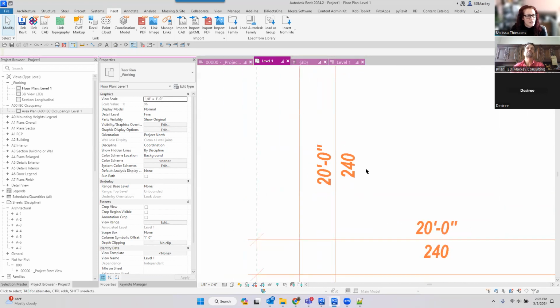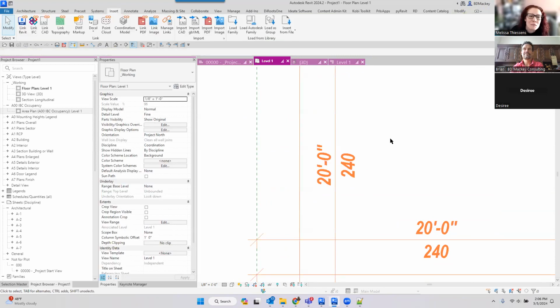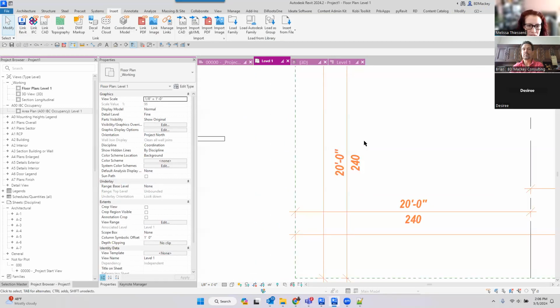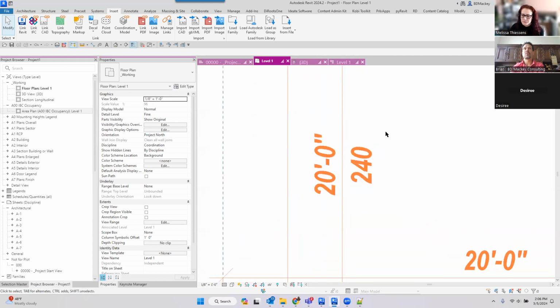I've been doing this for years. So I don't know if it's different if it's metric versus imperial, but I don't get this at all. Is it maybe a very small dimension or something? Yeah, because we have our check one where the bottom dimension is a foot long, but I have it suppressing those numbers if it's not there. And maybe it's a font issue. I don't know what font you're using, Ben. Maybe just try changing the font and see if that fixes it.